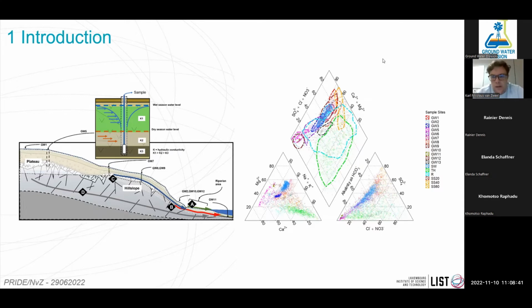So in terms of what is happening in flow generation, the whole PhD project is centered around trying to figure out how to predict the discharge chemistry, meaning the little stream in the catchment. A lot of isotope work has been done and they are fairly confident with the type of flow lines that you can observe in terms of stream flow generation, because what is often seen in headwater catchments is a double peak flood response. So in terms of rainfall, you have an initial hydrograph peak, and then it subsides, and then the secondary peak, or a much larger and continuous peak, arrives. So it is mobilization of older and newer waters that is stored in the catchment.